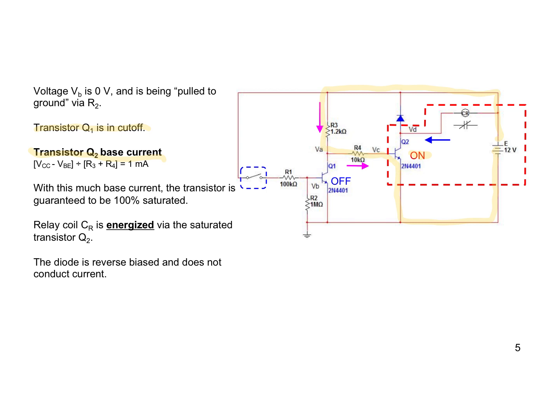So the idea is to use Q1 and Q2 as on-off switches. And in this case, with the control switch in the open position, we just saw that Q1 has no base current, so it's in cutoff. Q2 has plenty of base current, so it's going to be saturated. And therefore, because it's saturated, it is essentially pulling its collector down to ground. Okay? And we are assuming that the collector to emitter voltage on Q2 is 0.